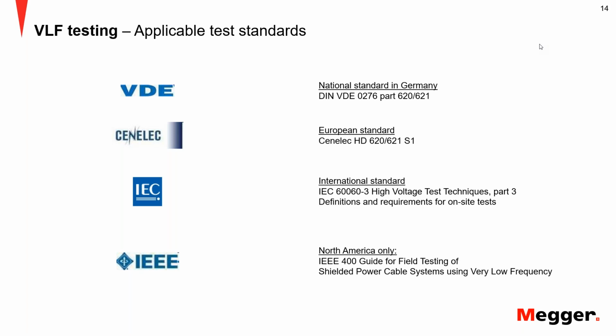If I may add to it, the withstand test is a go, no-go test. You want to see, does it hold or doesn't it hold? Whereas the tan delta test is a diagnostic test, and on purpose, you don't want to drive a diagnostic test to the limit where it could create a failure.